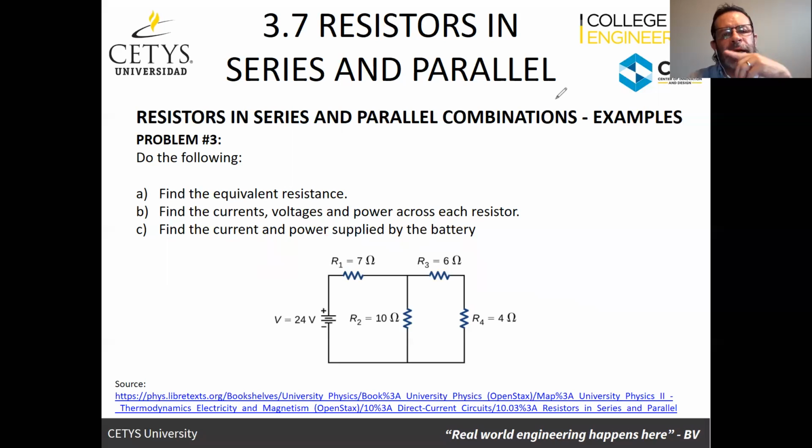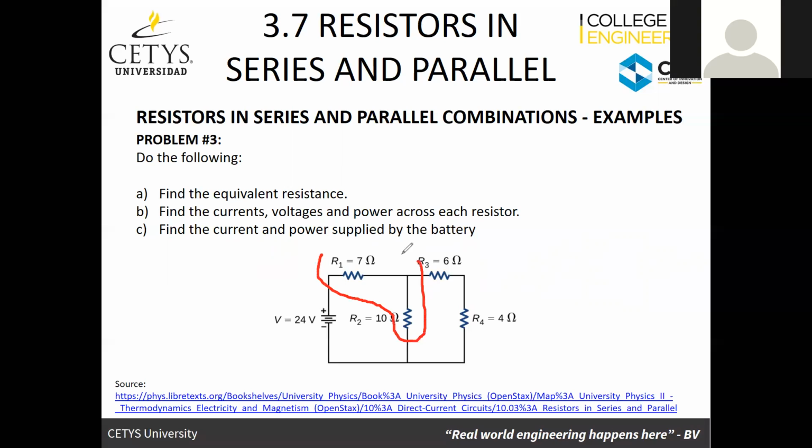Now let's look at what Carmina was saying. So Carmina, you were saying we're going to grab R1 and R2. Yeah, but I see now that they're connected with the two arms, right? Yes. So it's, parallel. Well, no, actually, first let's look at this. Are they connected in series? No, because we've got something else here. You see that? So they're not in series because we've got a separation here. For them to be connected in series, there should be nothing here.